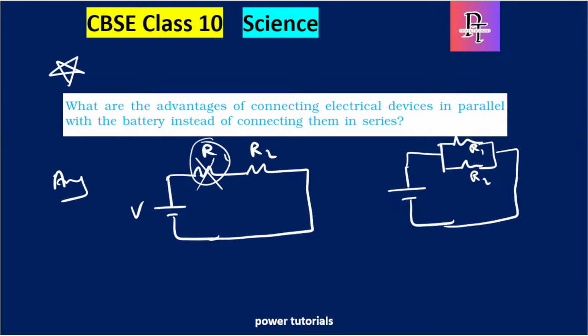So what will happen? This circuit will become an open circuit. Because of this issue, this resistor also will not get current through it because it is getting stopped here itself. The same malfunction, suppose it happens at this point in the parallel circuit, but still the current will flow through R2 without any change. It can get high currents, I can agree, but still the circuit will get the current. Here the current is not even getting.